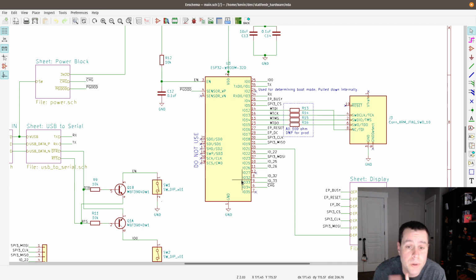So the battery can go up to 4.2 volts. The ESP is running at 3.3, and the swing on the ADC, I believe, is up to 3.6 volts. But reading through forums, it's not great. And so what you do is, it works best if you can get the range down within 1.1 volt. So if you can get the 4.2 translated down to 1.1 volt so that when the ADC reads 1.1 volt it's fully charged, and then as it dies off, you read lower and lower values. Maybe I should just play with that.